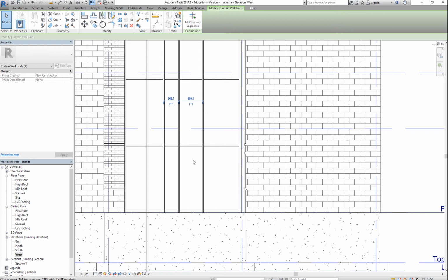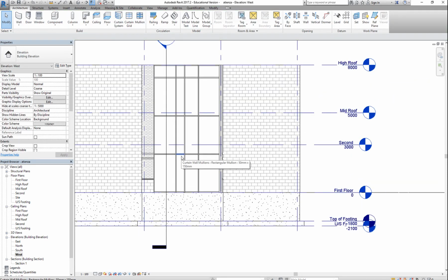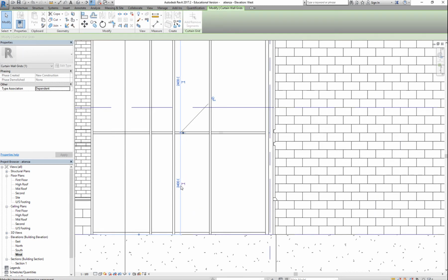Now, for your door, you also need to check the height. So if I hit the tab key, you want to select the grid. Okay, so that's about 2400. So maybe the height is just 2100. Okay. Oops, didn't change. 2100. Enter. It's pinned down, so let me unpin that. 2100. There you go. So I have a 2100 by 900. I think that's a good opening.